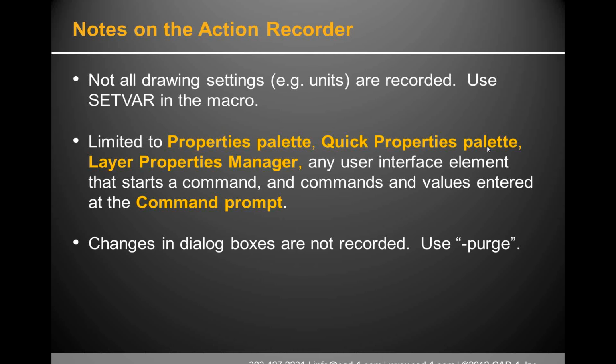Correct. Yeah, registry apps are one of those things that, about a year ago, I did a webinar on cleaning up drawings that have gone bad, and one of the things we talked about was purging registry apps, or regapps. We'll see those here in a little bit, as an example of how we might use this. They're kind of hidden things in the background of your drawing, and getting rid of those will help reduce your file size and improve its stability. So using this particular form of the command, -purge, is going to give you better access to some of those tools.